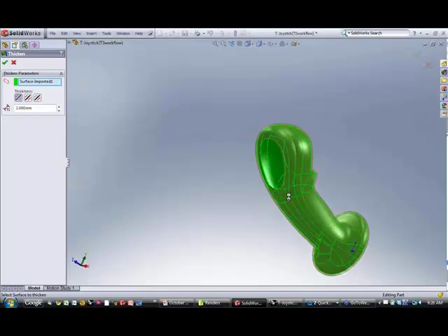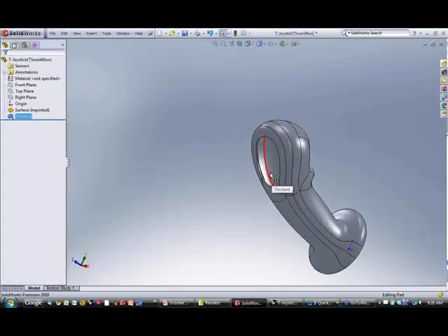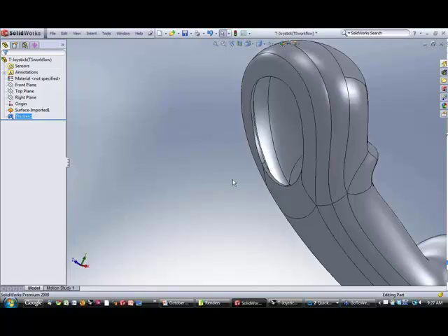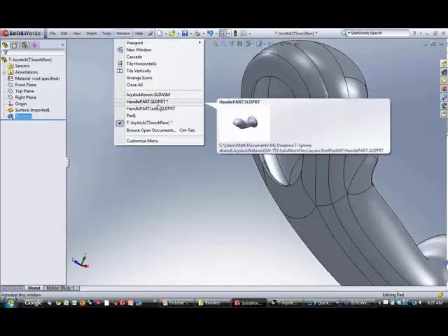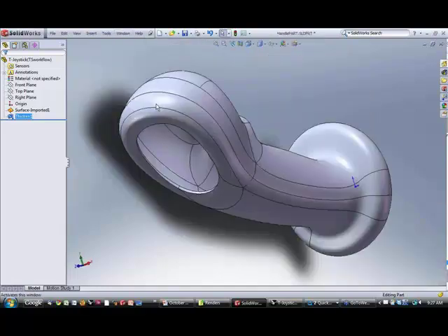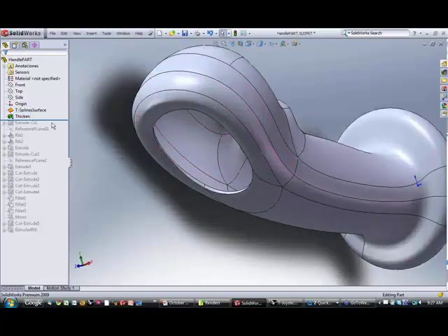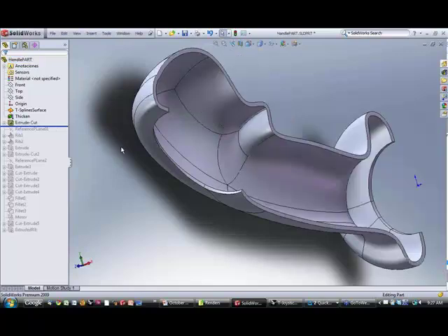And turn this into a solid. So you can see now this is a solid, and then we can perform any other operation in SolidWorks on the model. So I've gone ahead and saved these ahead of time. But here we're at the point where we've created a solid. I'll just step through the feature tree to illustrate how this works just like any other geometry in SolidWorks.